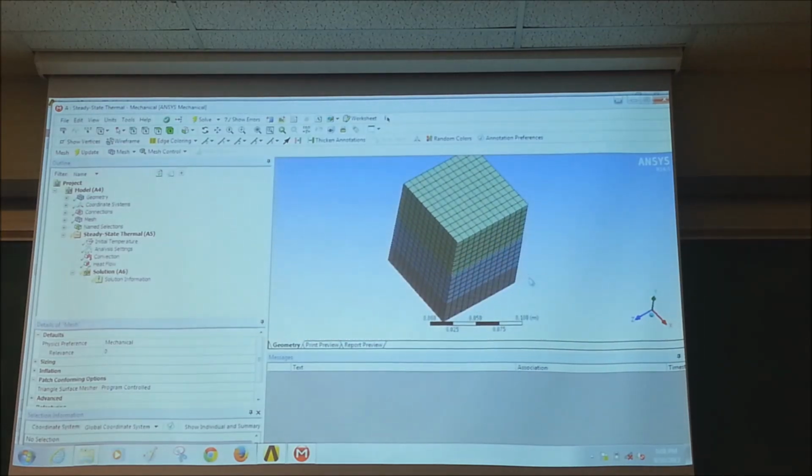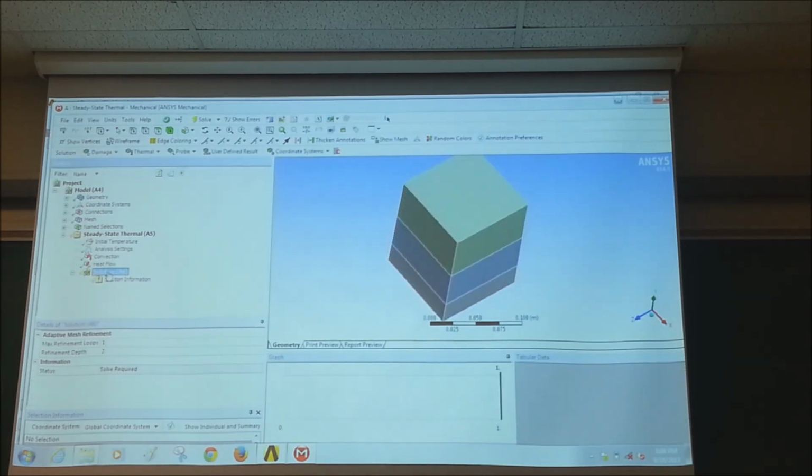What about the sides? Insulated. If you don't do anything, it's adiabatic. So you have to know the physics. In other words, you're not violating basic principles. You are applying a boundary condition, it just so happens to be adiabatic. So you're good to go, really. You got the boundary condition, but you didn't put in the material properties, right? Block 1.